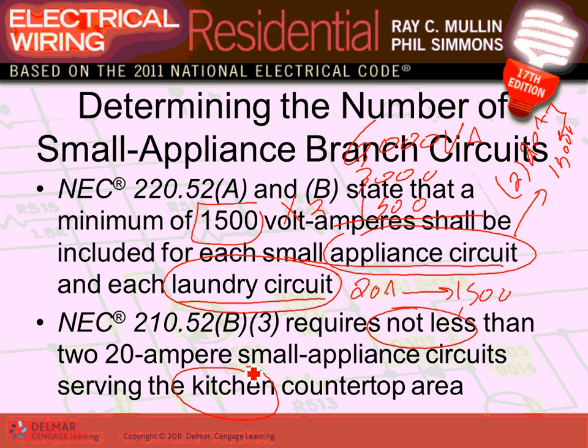The bathroom one does not have volt-amps with it. Don't ask me why. Dedicated circuit, above and beyond, but it doesn't have load though. These are 20 amp dedicated circuits for the kitchen and the laundry, and they also have to accommodate the load.